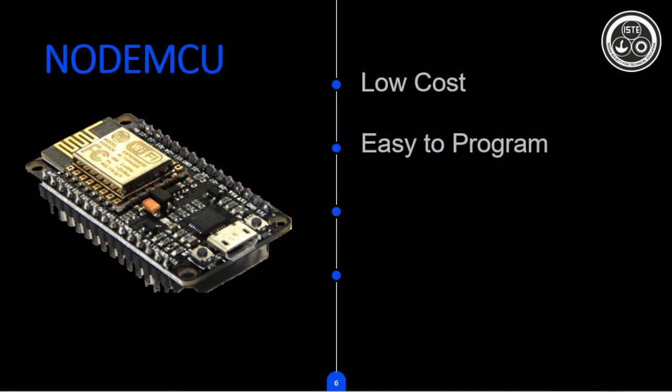So I will say 8051 is just a microcontroller. It does not have a development kit. If you want to develop a development kit for it, it will cost around 1000 rupees or 1200 rupees, like that. So why so? The reason is we cannot directly program the 8051 microcontrollers using our computers or desktops. It requires a JTAG or some kind of circuits which converts UART signals to the microcontroller signals, like we say TTL, transistor-transistor logic signals, and we need several circuits. We need a power circuit to power the thing. We need voltage regulators to make the 8051 power up. We need several things, right?